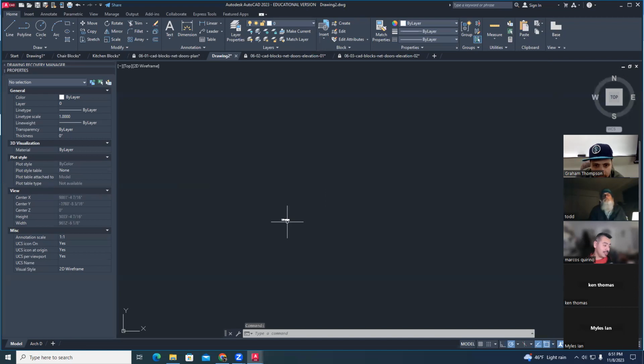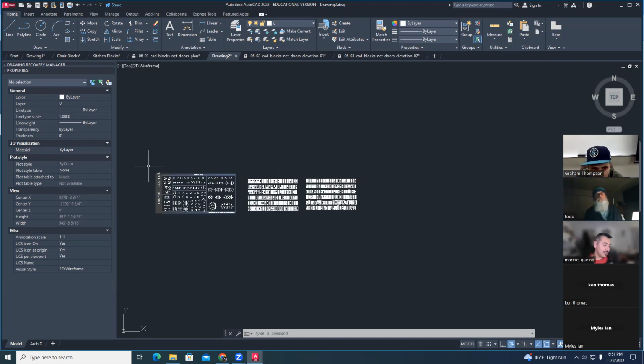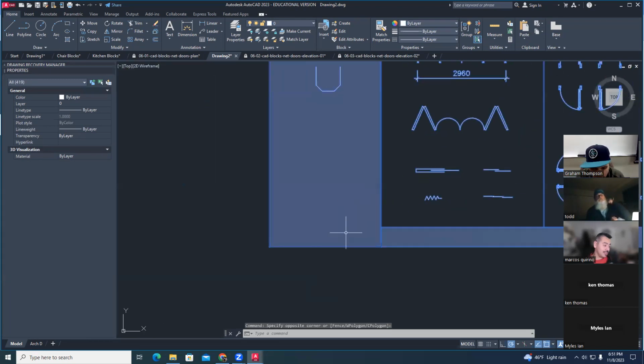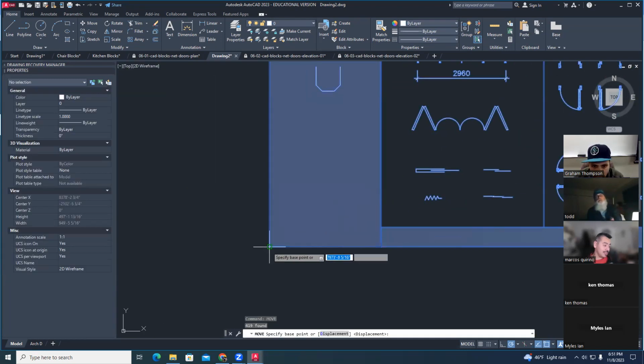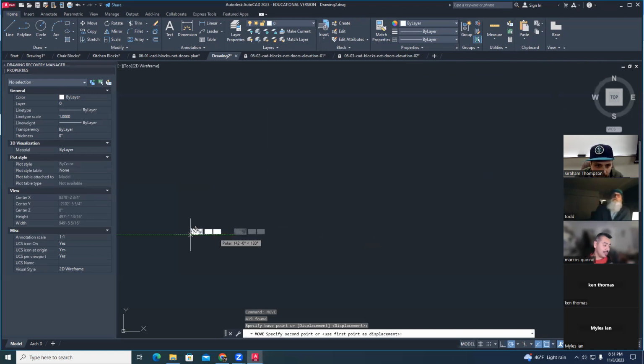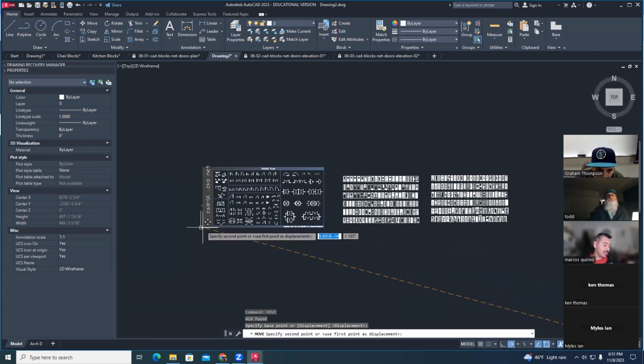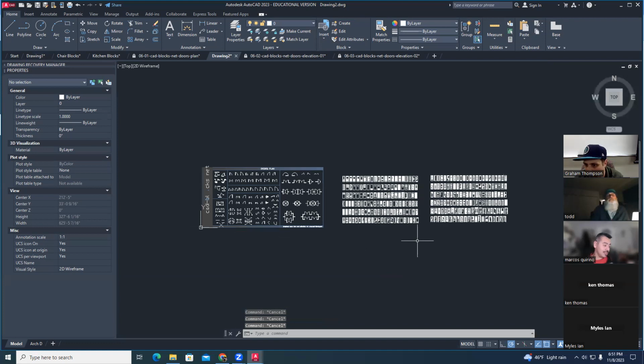DWG. Last but not least, the last thing I do once I scale it: I said I didn't care where it scales from because we're going to move it. So I click the whole thing, select it, come in here to the bottom corner, type in move, click that base point, and just to make it nice and easy, put it right near the origin. That way, when you open up the file, you're not having to look 5 miles out in the woods for it, right? Okay.